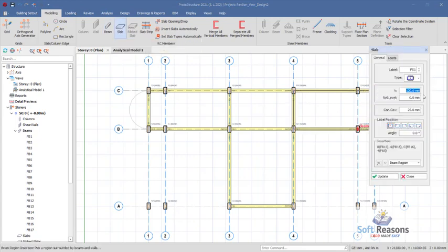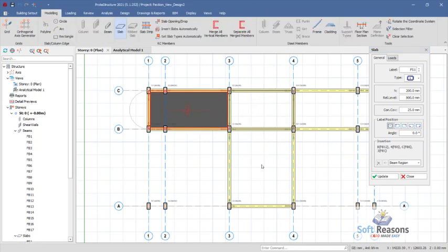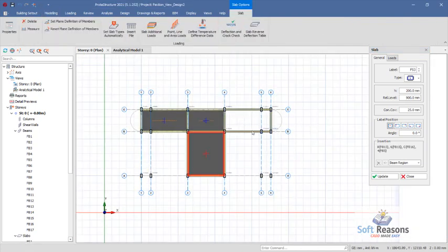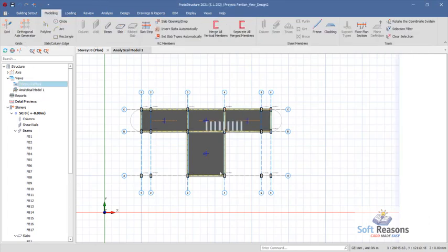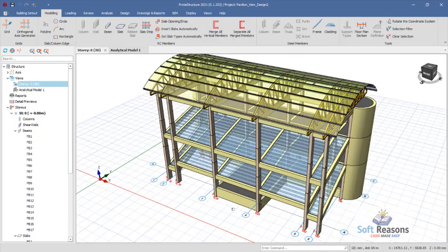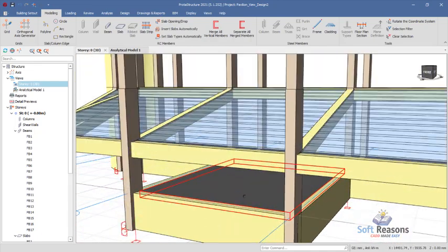The thickness is going to be 200, and the relative level we'll be considering is going to be 900, because 1100 minus 200 gives us 900. With this, we can insert the slab at the accurate level we intended. Then you can navigate to the 3D to see what you've done. You can see it's properly placed successfully.